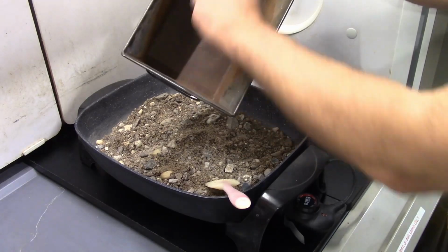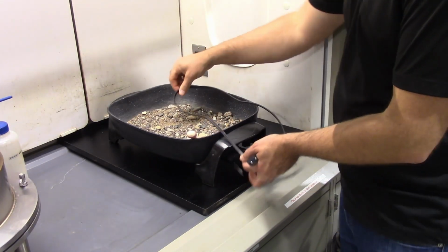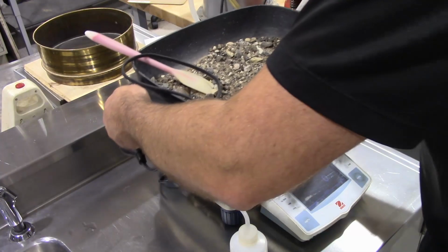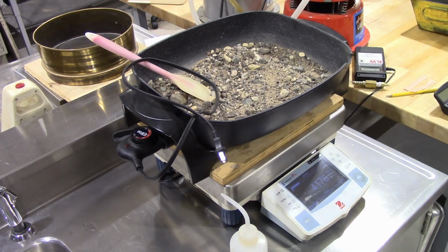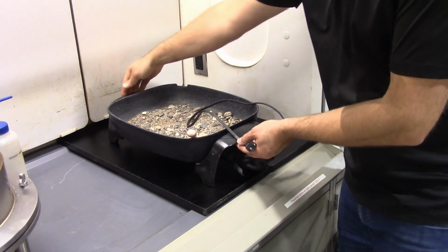The material should be fully dried. If the paper curl method is not appropriate to verify the condition of the material, the constant weight method must be utilized. This involves weighing the container and sample, waiting a period of 10 minutes, and confirming that the sample is no longer losing weight.